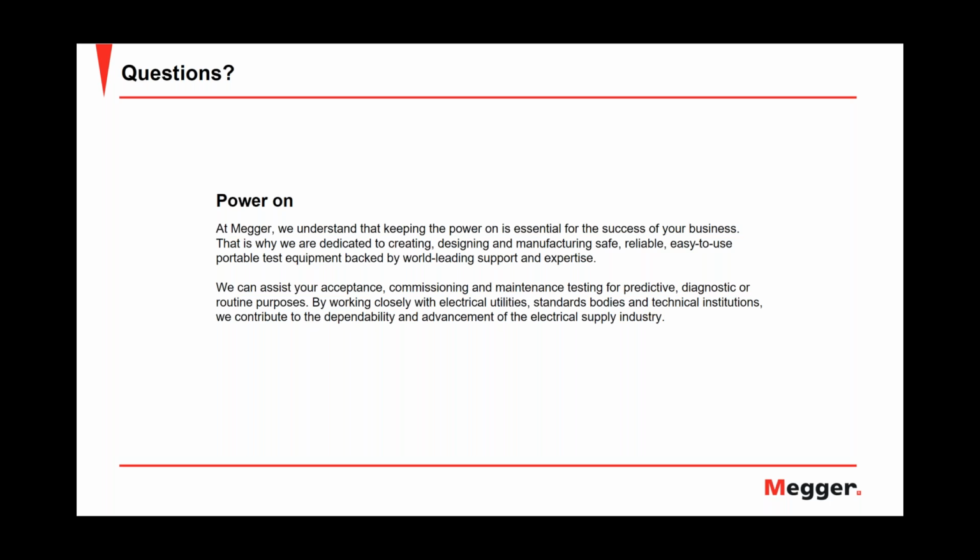So in the moment where we have a flashover, we're using the TDR now and shooting the radar pulse in, and the radar sees a short circuit and gives us a negative reflection. That is how that works, and that's why it's called arc reflection. Without an arc, I cannot do arc reflection method. That's what Javier was saying. If we have a dead short, there is no arc, I cannot find it with arc reflection method.